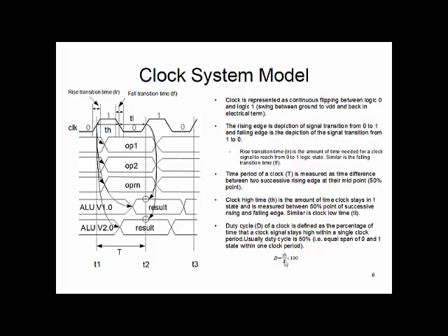Duty cycle is 45%, and I know, let's say, t high is 0.45 nanosecond. Then what is my time period? We can calculate it from this formula. We have this known factor, t high, which is 0.45 nanosecond, for example, multiplied by 100 divided by t, equals that duty ratio of 45% we have been given. So you solve the equation, you get the time period. Keep these formulas in mind.